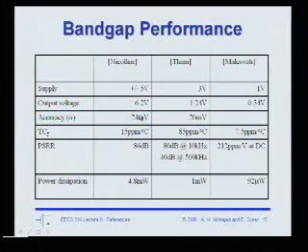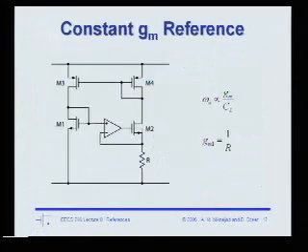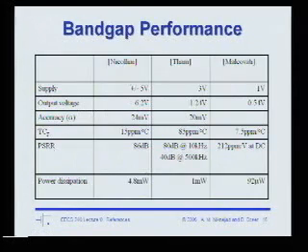The output voltage varies 20 millivolts relative to 6.2 volts. So definitely this is more accurate than the second one. You can see the power supplies are about the same at low frequencies. Again, without the numbers at high frequencies, it's hard to compare. Okay, questions?